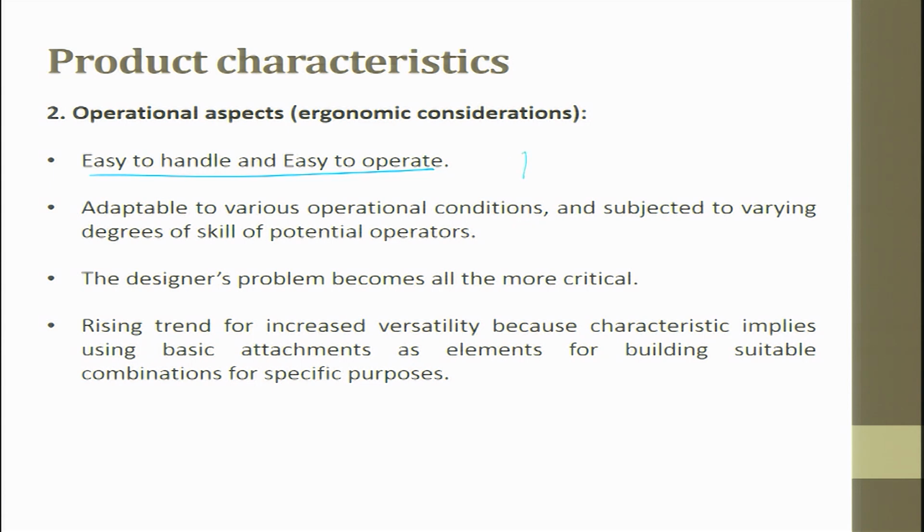Many a times the AC whatever we buy in India, they conk off when the temperature goes above 48 degrees or 47 degrees, because there is too much heat generation in the compressor side. The heat in the compressor could not be extracted, so it conks off. So, until the compressor is cooled, your AC will not work.